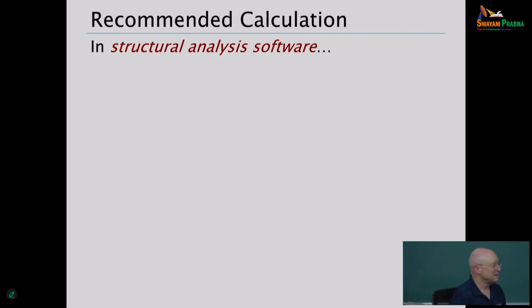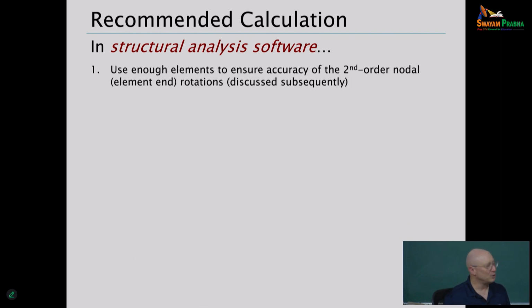Now, a general recommendation, if you're a software provider or if you're writing your own software, is okay, I can handle this, and of course I could handle it by solving the governing differential equations and implementing that. But short of doing that, for structural analysis, we need to ensure that the engineer is using enough elements to have an accurate nodal solution.